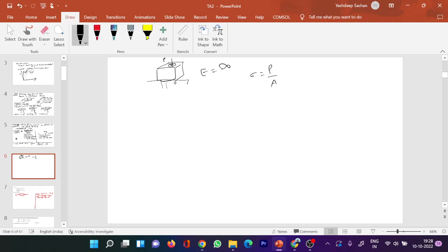Okay sir. So stress will change from plane to plane now. Here the stress on every plane is going to change. Stress would be different in another plane. Loading would be changed, so stress changes on the different planes. So here would be P by A, and here you are saying zero area it is acting, so here stress would be infinite now because area is zero. So from P by A to infinite it will change from plane to plane, if you look at it that way.